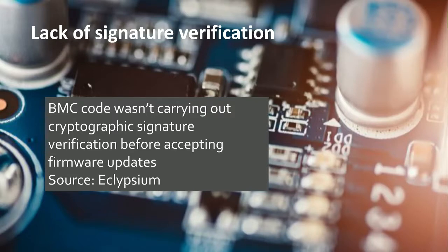And part of the problem there is when either the private key is compromised or it's lost, stolen, then it's a challenge to update the public key on the devices. So when you get to that state where literally the device gets bricked, the only way to send an update is literally by bypassing the signature verification.